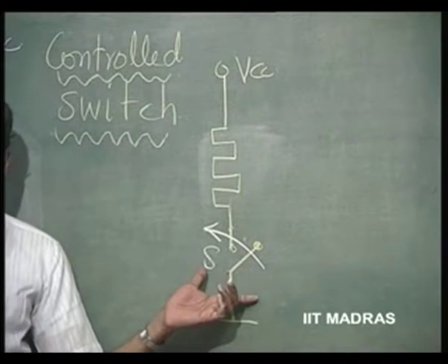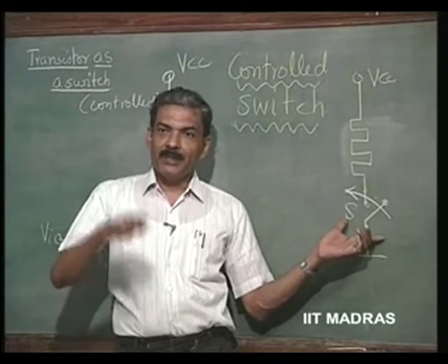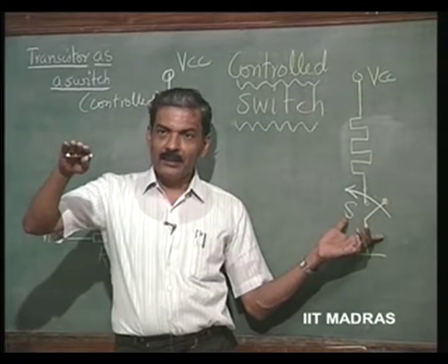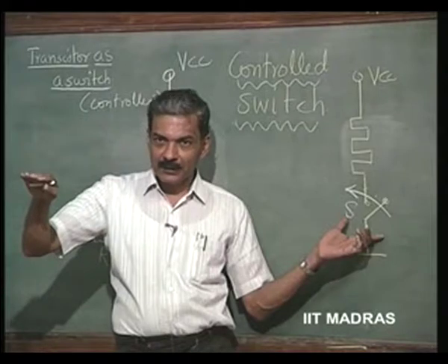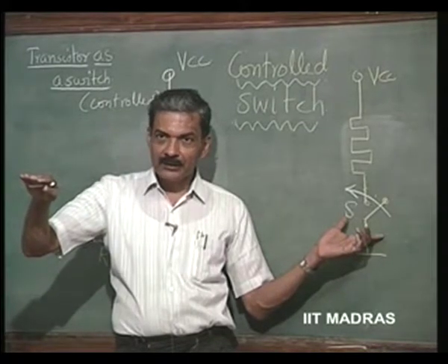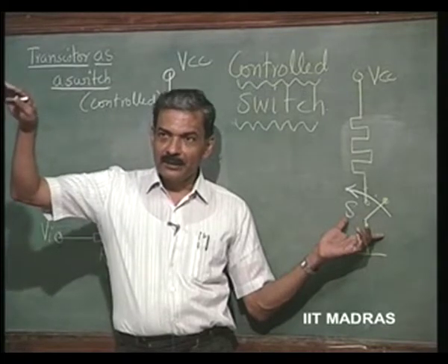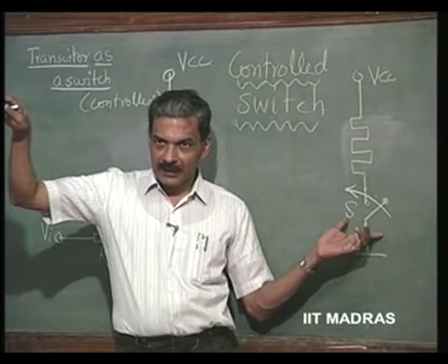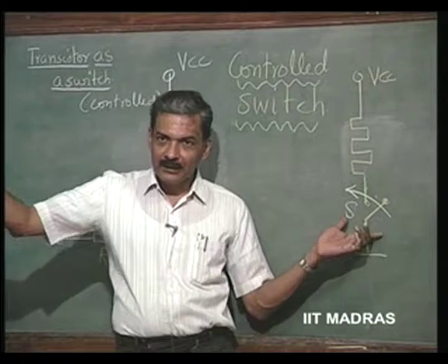Our fridge is nothing but an on-off controller, where the moment we switch it on, a certain temperature is reached, and as soon as it falls below a certain set point, the compressor is switched on again, and it will get cooled again to the particular temperature at which we want it. Again the power is switched off, like that.